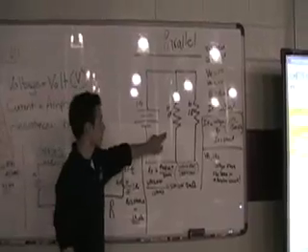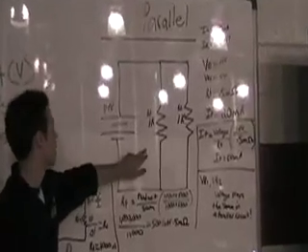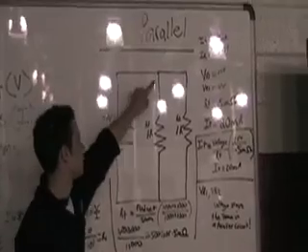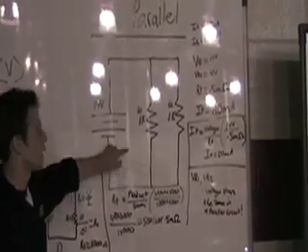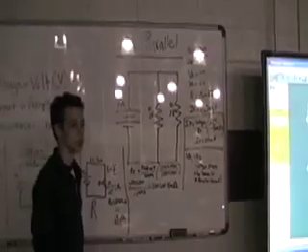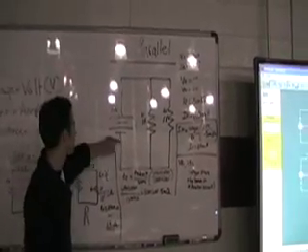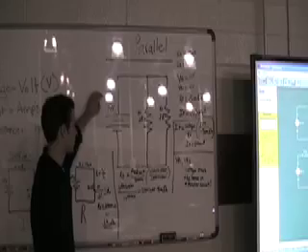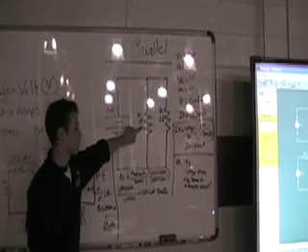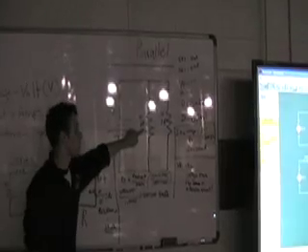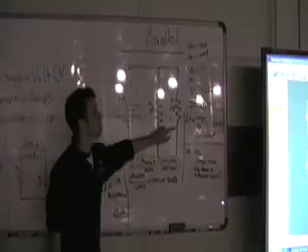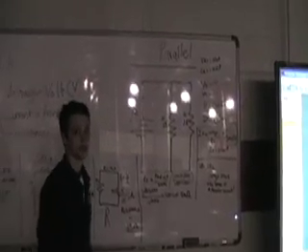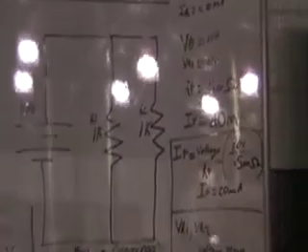Since the voltage stays the same in a parallel circuit, 10 volts will travel through both points in the circuit and stay the same. Current, on the other hand, will change. You'll have to take 10 volts over the 1K resistor. That will leave you with 10 milliamps. But since they're both 1K resistors, they will both be 10 milliamps for this circuit.